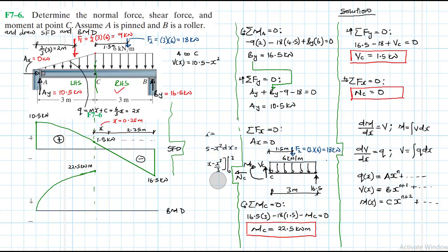Let me just clear my little space. So what do we have there? There we have the shear, which is positive and is again decreasing linearly, so you expect moment to be quadratic. And then the slope for moment will also be positive but decreasing. And this magnitude is just the area under the shear diagram.